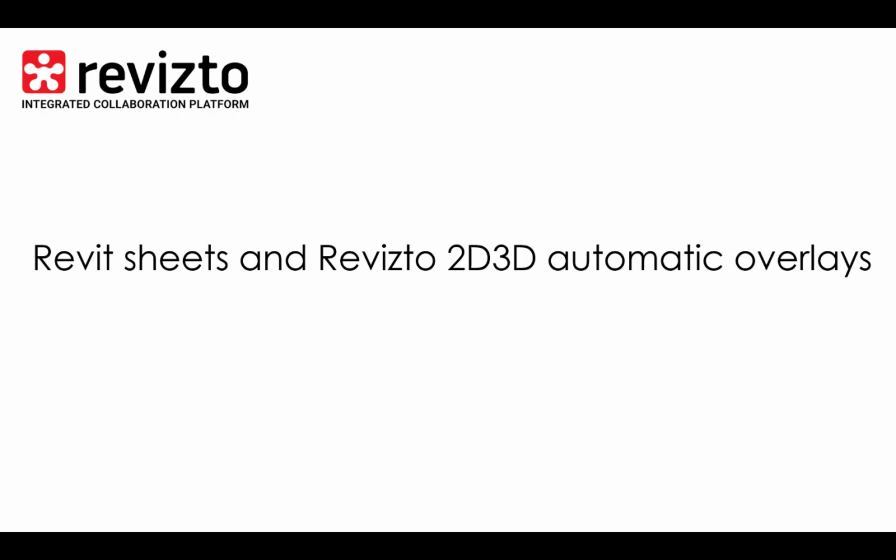In this video I will run through how to set up Revit sheet and viewpoint settings and how the automatic sheet overlay works inside Revizto. So we'll be looking at floor plans, elevations, sections, details, publishing sheet coordinates only, and integrations with Revizto, specifically SharePoint, and how we can send sheets which are sitting on a CDE like SharePoint to Revizto's 2D environment.